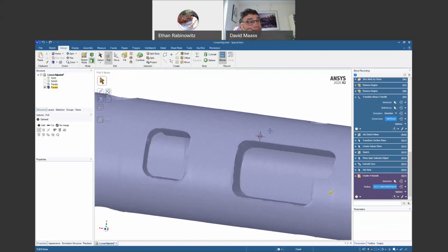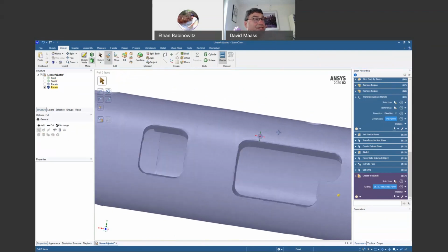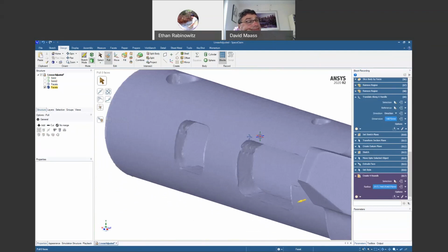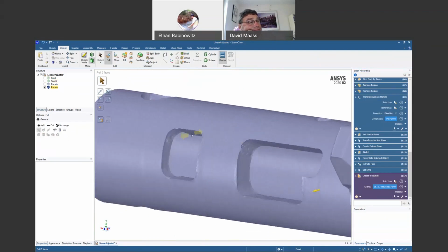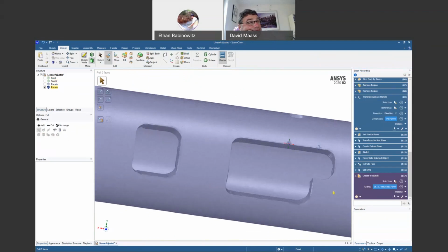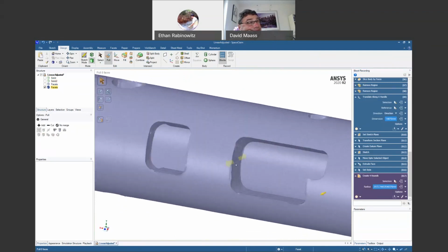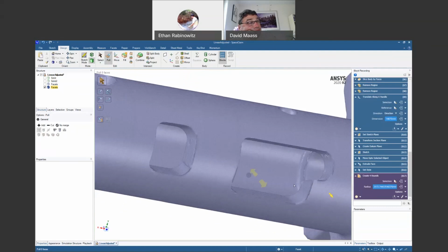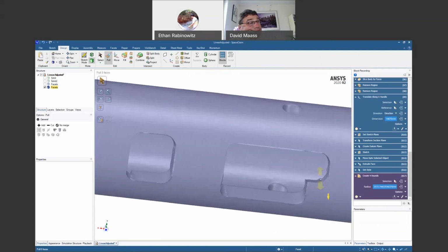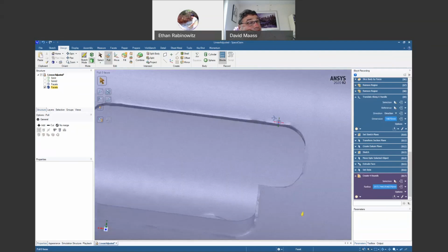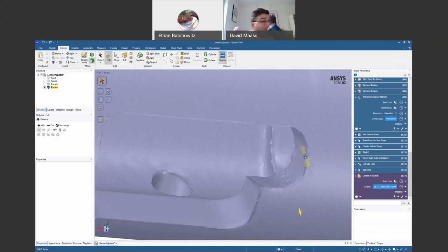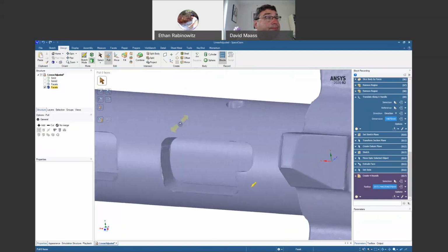This other one. Does it have a similar cross section? Yeah, pretty much. We could do one of two things. Either what we just did, and I would probably do something like, through here, then move it up to this face, cut it down over to here, and then we would just essentially repeat that. I would put the cross section through here, create the sketch, move it to this face, and this part will already be open. So then we just make a cut into here, and the two cuts would be one big pocket.